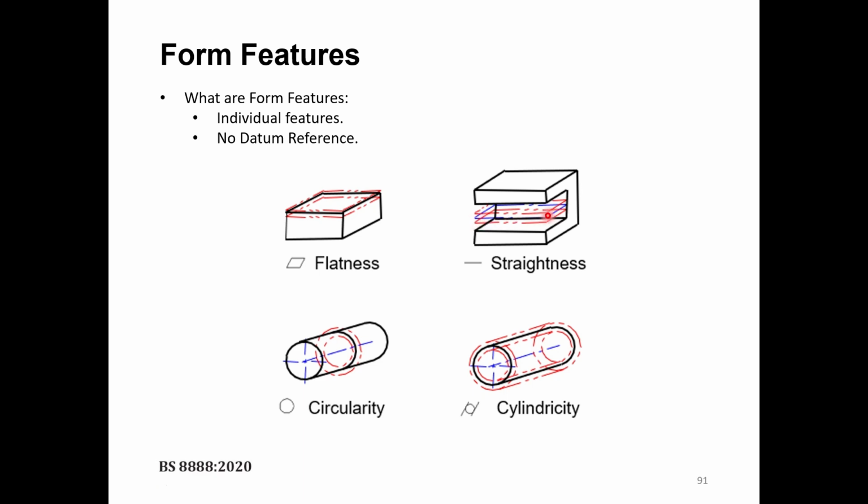So if you keep drawing any line here or any plane between these two planes, regardless of its angle, it should be considered as acceptable, as long as this blue plane here does not go above or below these two planes that define the tolerance.